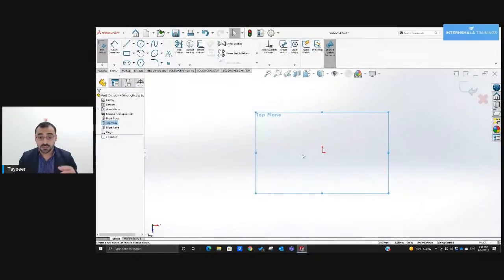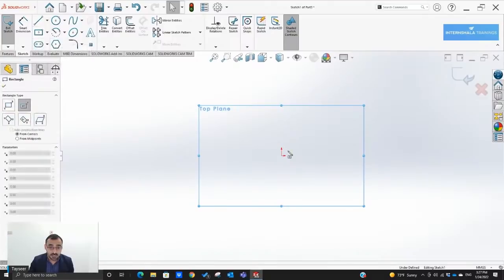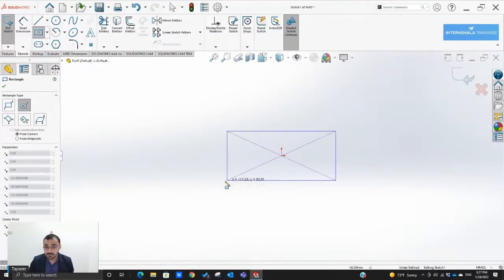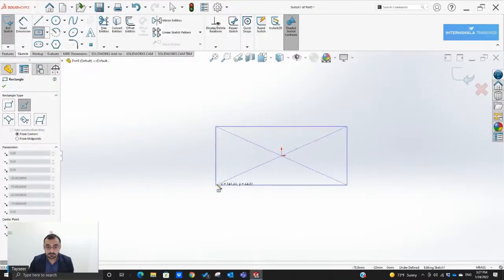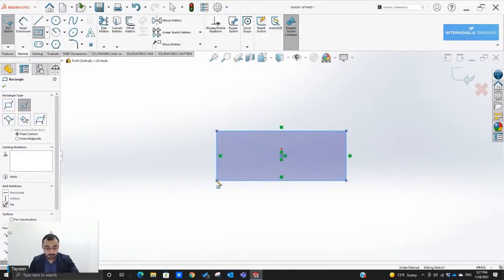And now I'm going to create a sketch of the top of that table. The top of the table, as seen in the napkin, is a square top with a side of 500 millimeters. So I'll go to the command manager here on the sketches and go to the rectangle shortcuts, select one type of rectangles, click on the center, and then expand, and then click again.